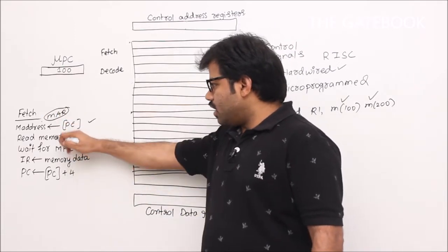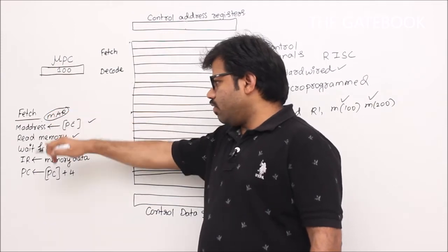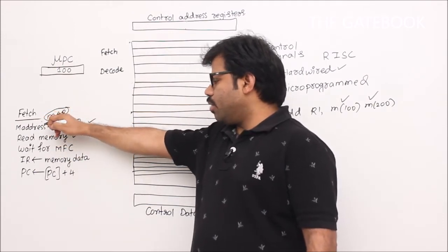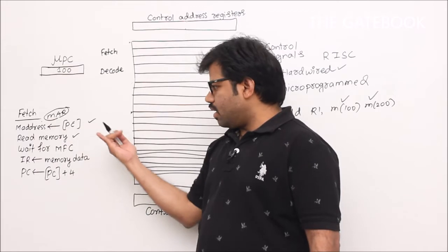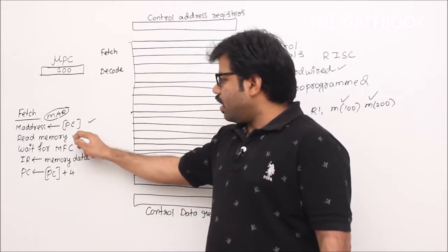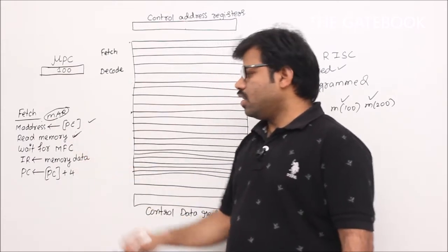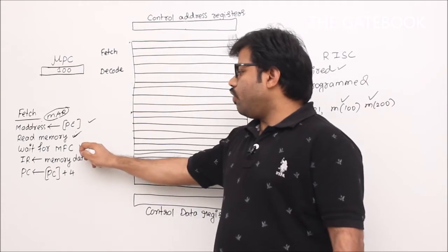That memory interface will work with this memory address register. Whatever address you show in the memory address register will be taken by that memory interface, and it will read the memory if you issue this operation. After that, we have to wait for this signal.